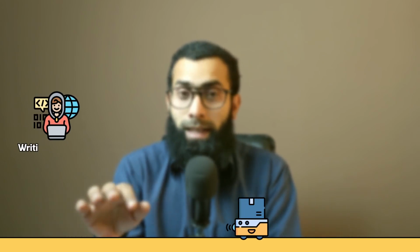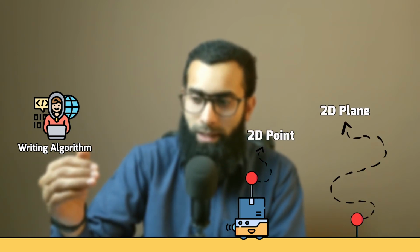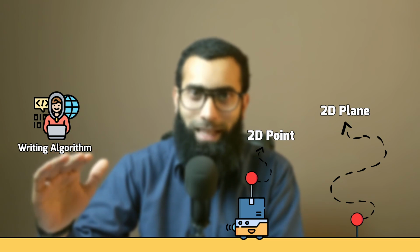Whenever it comes to motion of a mobile robot and you are writing an algorithm, you have to consider the mobile robot as a 2D point on a 2D plane, on the condition that your robot is moving on a plane surface. So when you are looking at your robot as a 2D point, you write the algorithm, you perform all of the mathematical operations on it, then you come back to the robotic domain. In that you just need to translate the positions of the point into velocities of a mobile robot, and that's the conversion you need to do. And you should always keep the relation of the motion and velocities and acceleration to the xy coordinates of the grid on which the robot is moving.